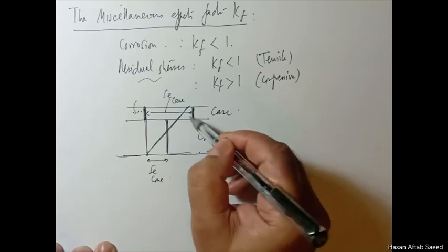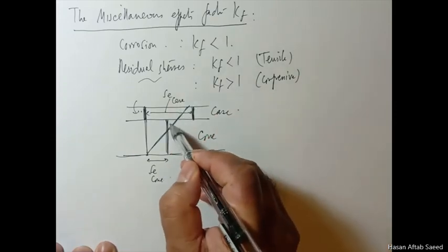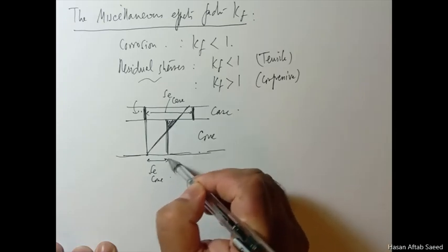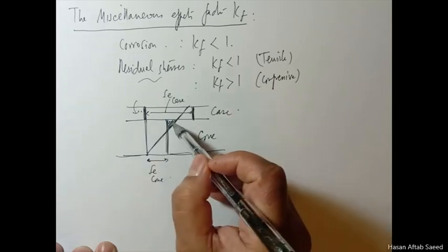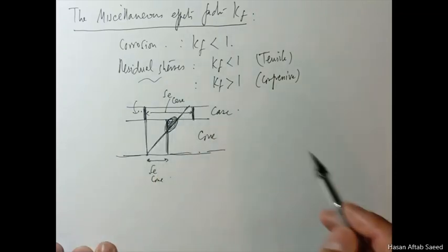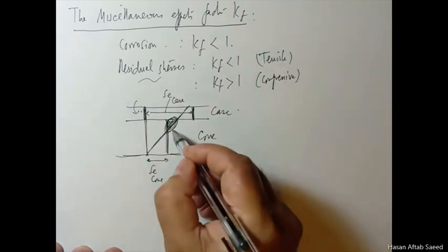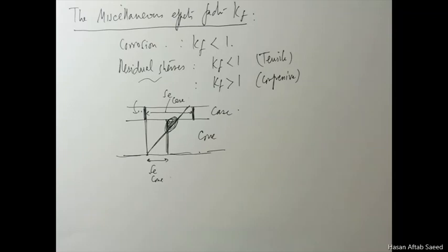and that's all right because the stress is less than the endurance limit, no problem, it should have infinite life. But if you see this here, you have this region where the core has a lower SE than the stress it is being subjected to, and if it's a bending fluctuating stress, then this component won't last forever, or what we call infinite life.